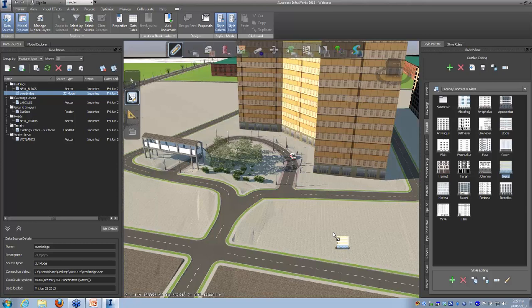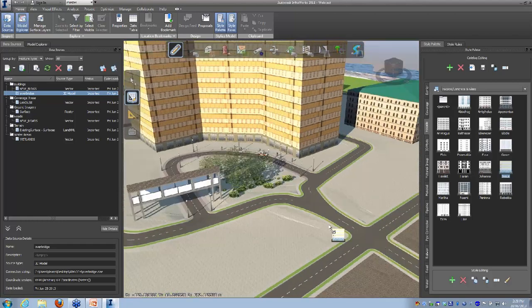There is the ability now in these roads, these new roads that are created, if you have the ultimate version of Infraworks, from the ultimate version of the infrastructure design suite, you can export road centre lines and profiles out to Civil 3D. So once you've finished playing around in here, you can take it to the first stage of the design process and get profiles of the roads and the 3D geometry of the road into Civil 3D as a starting point for where you can start your designs once you finish playing around in here and moving things around with stakeholders.